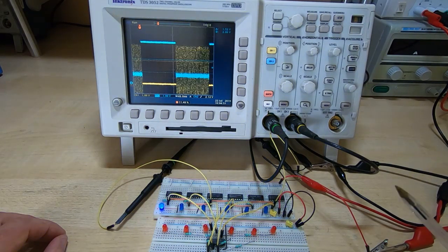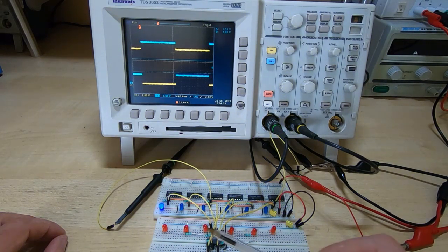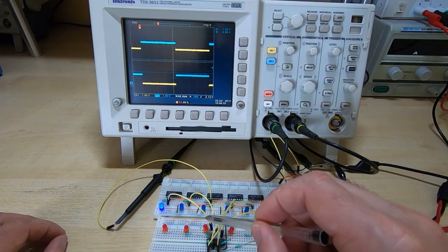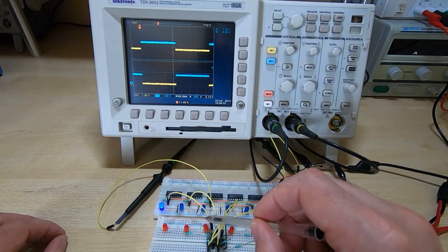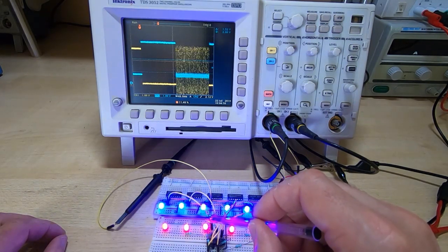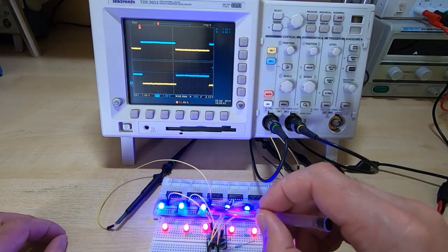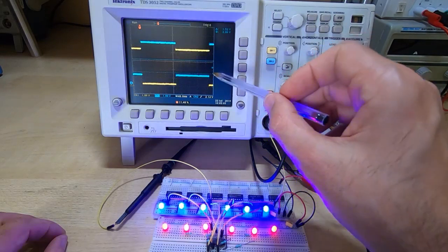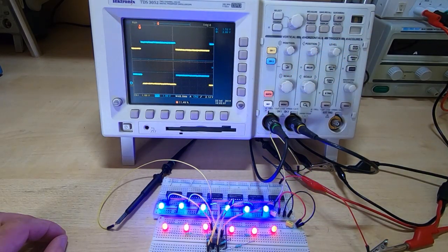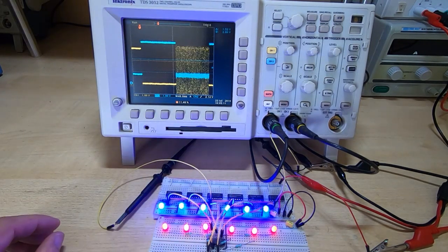And that can be very misleading. You might think it's working fine if you're looking at the signal with a low frequency device like a probe or something like that, a logic probe. But on a scope where you can see the high frequency, you can see that the instability is quite severe. And this is caused by interaction between the various devices.